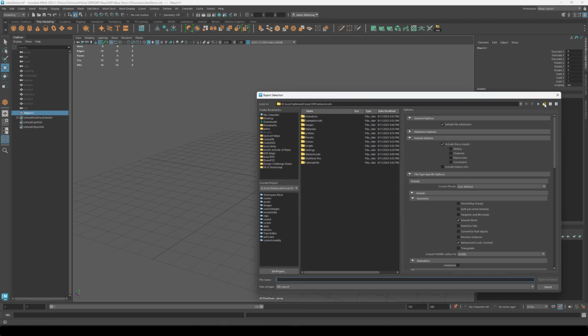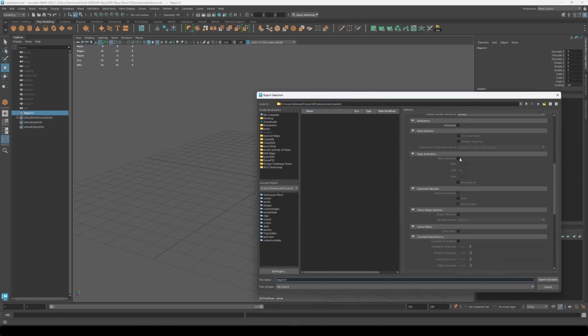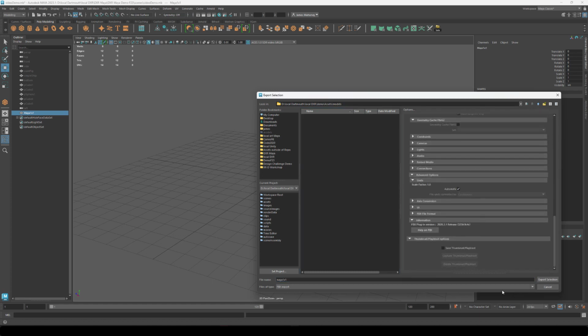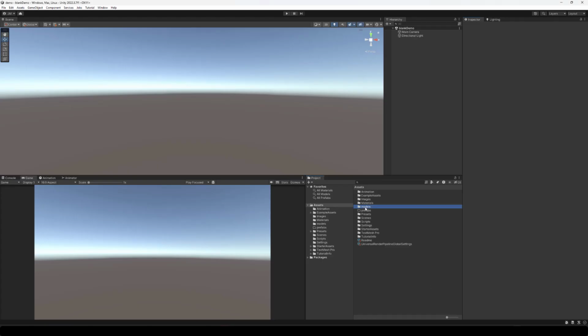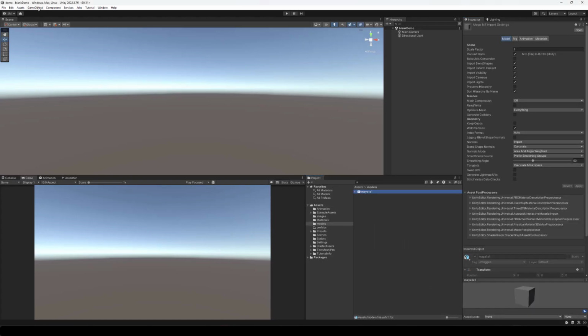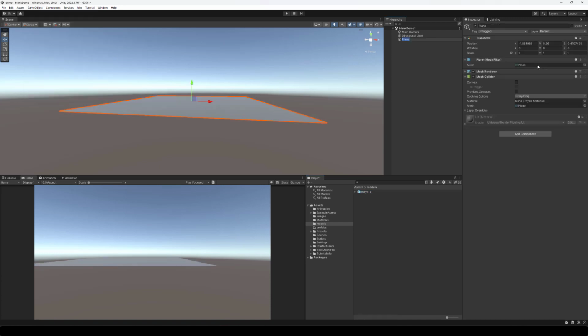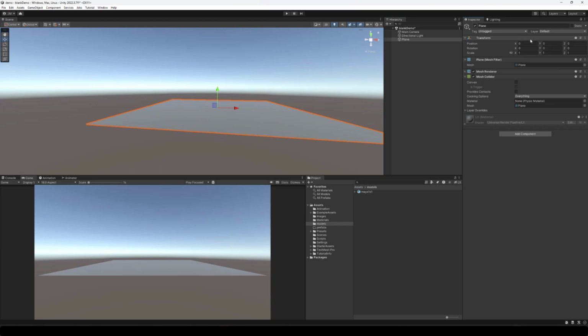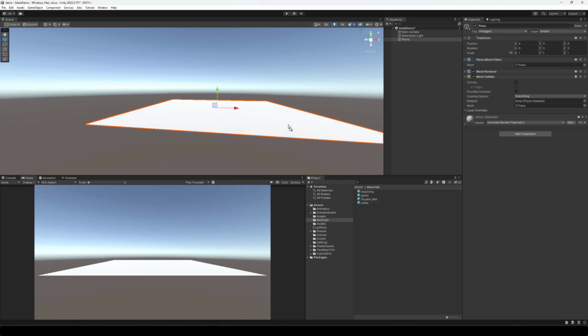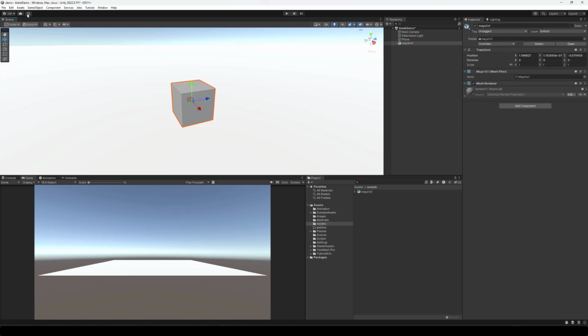Create a new folder called Models, if there isn't one already. In the folder, save your object with the name Maya 1 by 1. In your Unity file, create a plane and name it Ground, and right-click on its transform bar in the inspector and choose Reset. Create a folder in your Projects panel under Assets called Materials, if there isn't one already, and create a new material, white, say, and assign that to the plane.